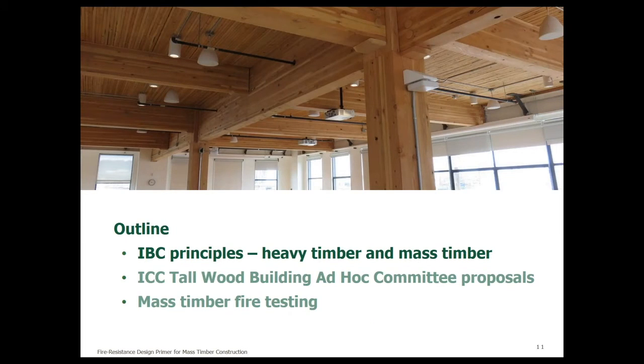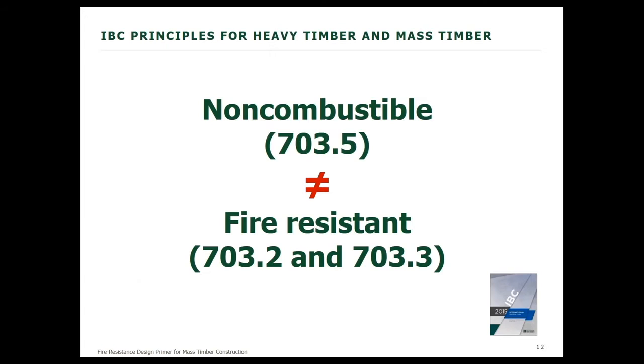Now I'll touch on the IBC principles associated with heavy timber and mass timber. Before we get too far into that, what I want to do is take a step back and look at some of the more basic principles of the IBC. Non-combustibility and fire resistance are two different things, and they each have their place in the code. The code requires non-combustible materials for some purposes and specific fire resistance ratings for others.